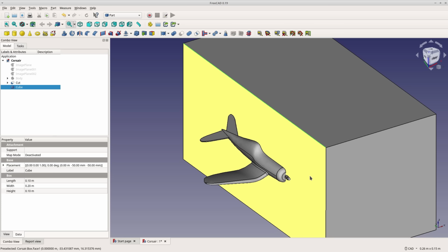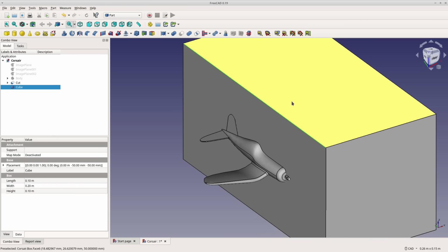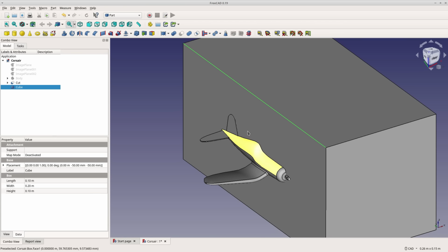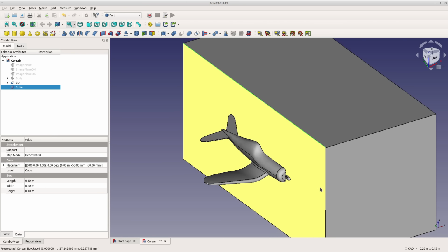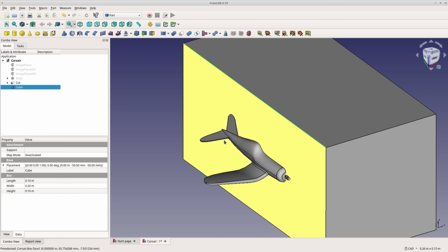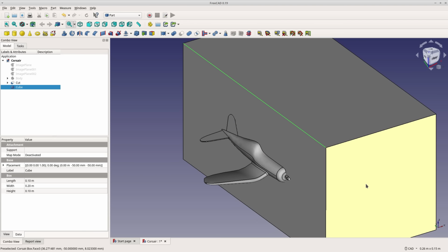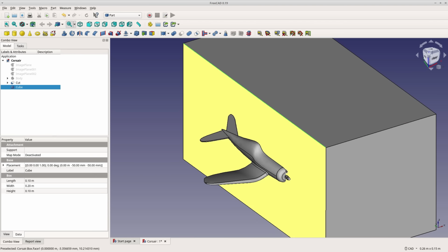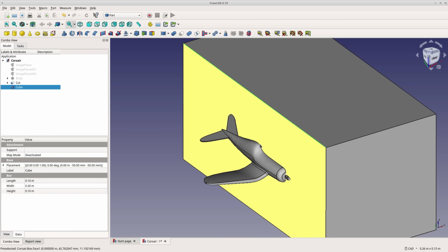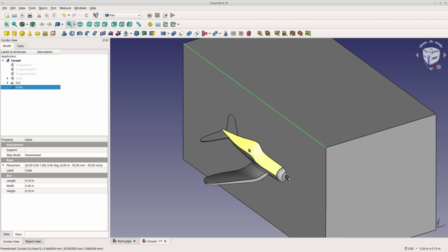Additionally, if we look at the envelope of our flow area, this is for a quick computation, right? Our flow area here is pretty short in front of the plane, and it doesn't go very far behind the plane. We generally want to take the length of the plane, or the length of whatever you wish to flow externally, and make it 10 times that length, and put it right in the middle. That's a general rule of thumb. And so we're not that far.